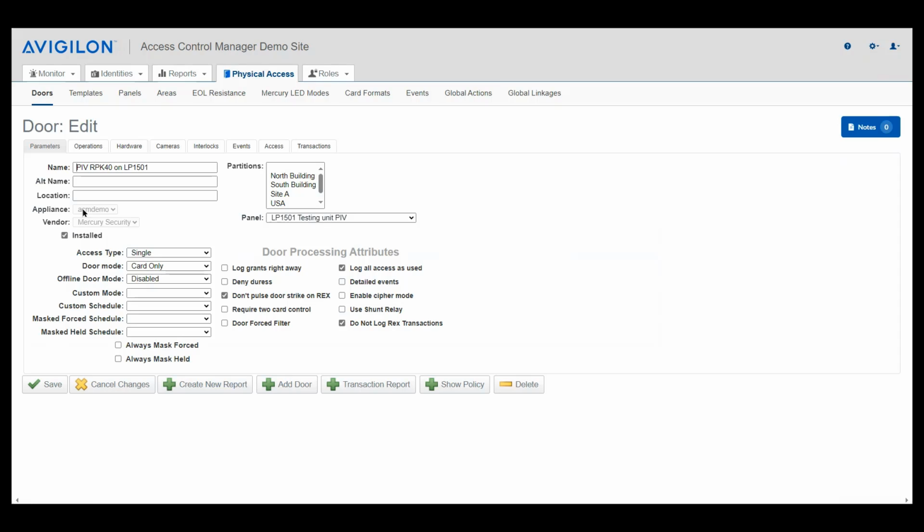And the reason I say that the 4502 is if later on, or in this transition phase, you don't have it configured to do full FIPS authentication, you have the hardware in place, so you can always add the software needed and the configuration to have a full FIPS solution. You won't have to replace any hardware, right? So you want to have the proper controller, LP4502, and the right PIV readers that go along with that. All right, now I'm using this reader here. As you notice, it is a 1501, so I'm not using that, just for pure sample, just to show you how to do this. So I have the reader already configured here in ACM. This is already added to ACM. There's a couple of things you need to do. First one is here.